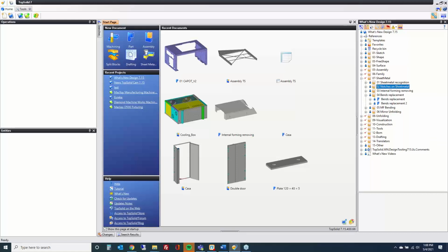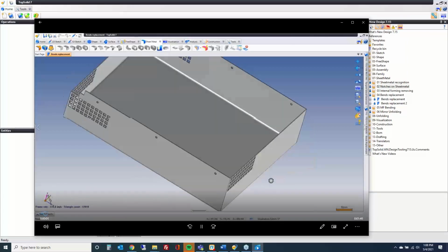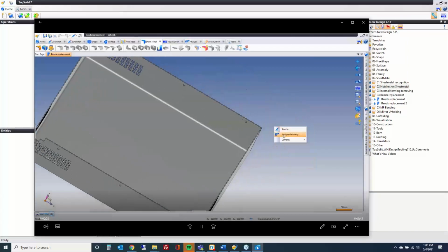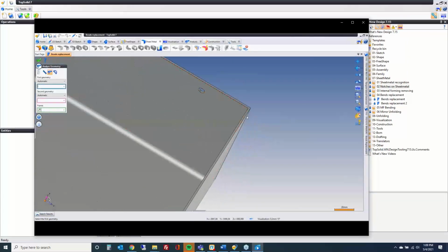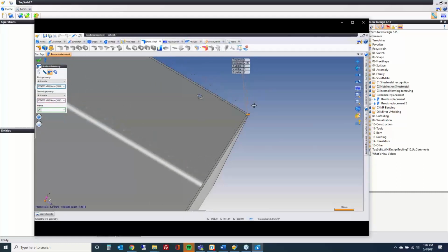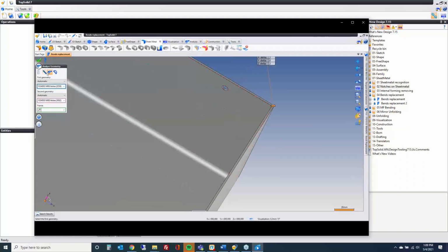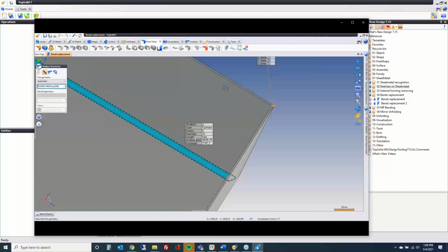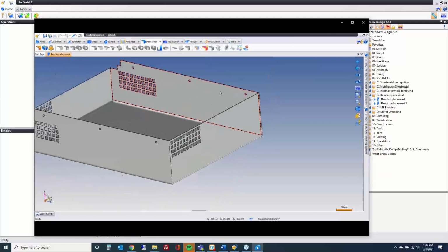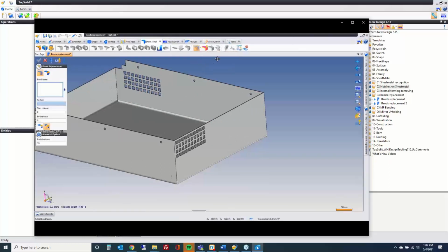Bend management. We're going to go to the next video on. The bend management command allows you to extract or replace bends on a part if the modeling of these parts is not perfect, for example. So the whole point here is we just want a fast way to be able to remove bend radiuses on this imported part because maybe they weren't added properly by whoever sent them to you.